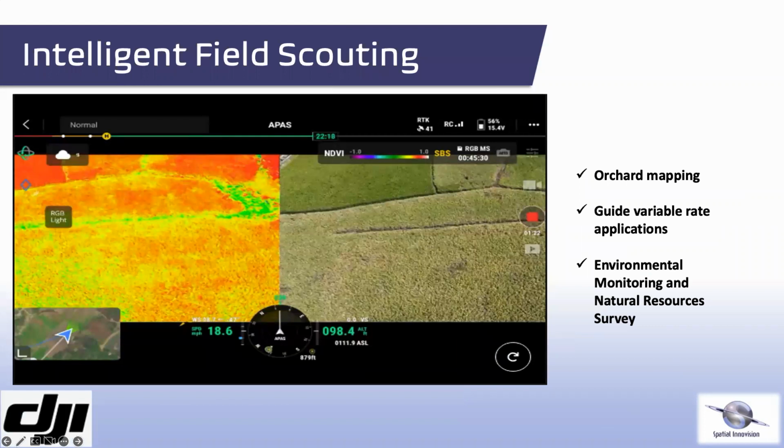It also has ArcGIS mapping. The Mavic 3M allows terrain follow aerial surveying of orchards, even on slope landscapes. Together with DJI Terra or the DJI Smart Farm platform, it can reconstruct high-resolution orchard maps, automatically identify the number of trees, distinguish trees from other obstacles or objects, and generate three-dimensional operational routes for agricultural drones, making operations safer and more efficient.